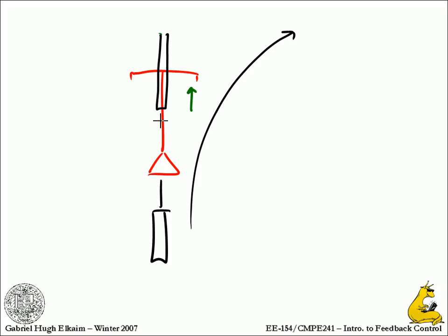To the right. Okay? So when you want to turn to the right, what you do is you torque the wheels to the left. Okay? You try to get the front of the wheel going to the left, and what that does is causes the precession on the wheel causes the bike to tilt over to the right. So you actually take the bike and you tilt it over. Once the bike is tilted, then the only path that keeps both wheels on is a circle. Right? And it will take that circle out.